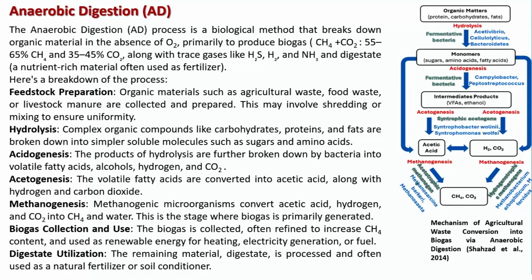And then acidogenesis, this is a very important one. The products of hydrolysis are further broken down by bacteria into volatile fatty acids, alcohol, hydrogen and carbon dioxide. And to do this, there are fermentative bacteria which are very proactive in making this process of acidogenesis.